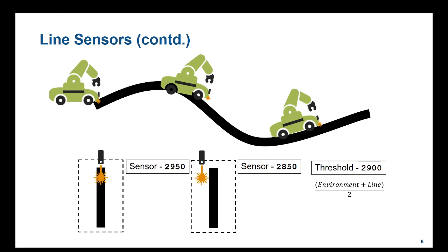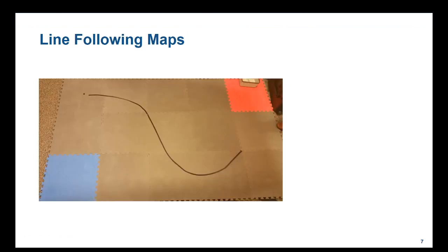So now that we have understood the characteristics of the real sensor, let's see how to bring this information into our simulation. In the real world, the robot travels over the map and the line sensor provides us a value corresponding to the surface it sees currently. For the simulation, we will take a picture of the full map and use a black and white version of that image to know where the lines are.